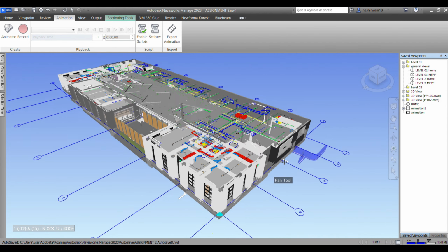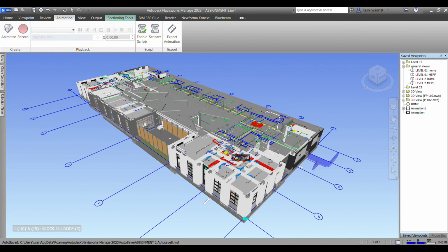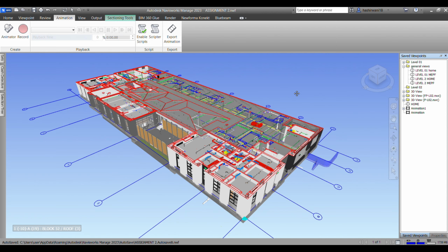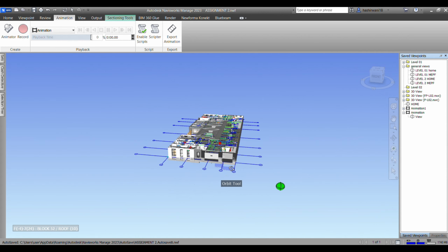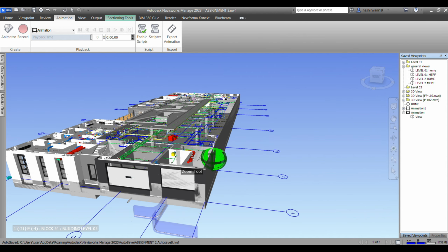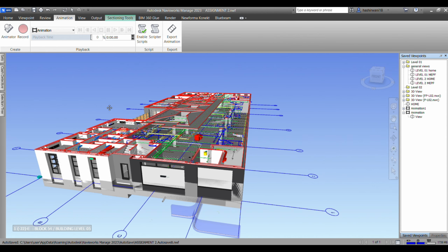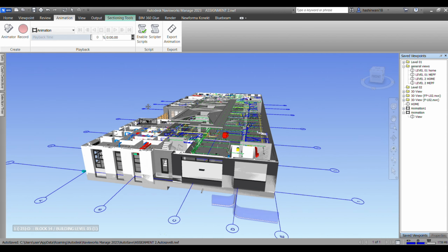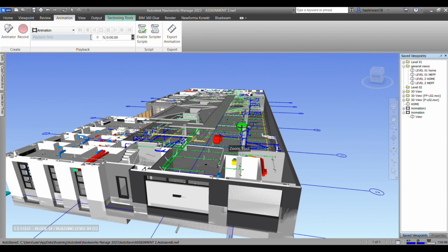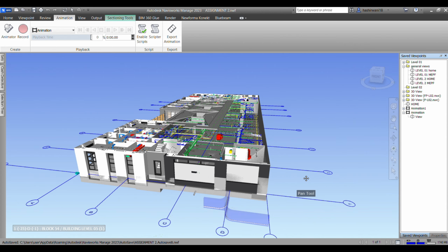So whenever I pan this mouse, for example, this is the first view range I want. This is the first scene that I want in my animation. So I'll just go here and right click on this animation. I'll just save this viewpoint. Now the next cut scene or view range that I want, I'll just move to that view range. None of this will get selected. Now if I'm panning here in this particular animation, that won't be recorded. Only the saved viewpoints will be recorded.